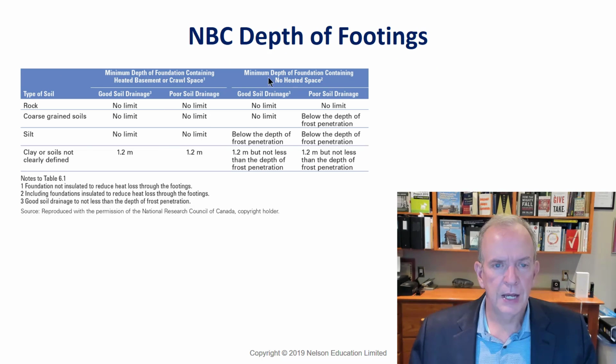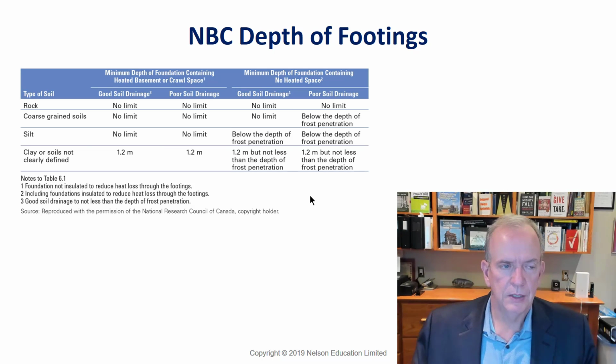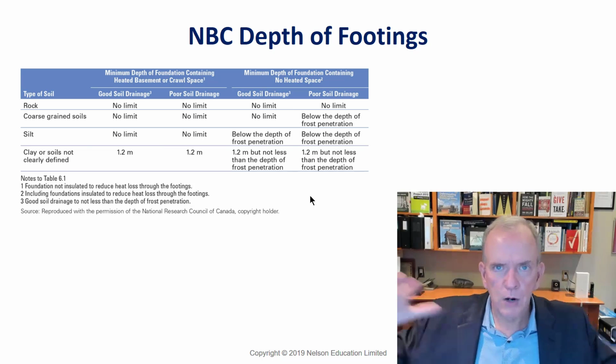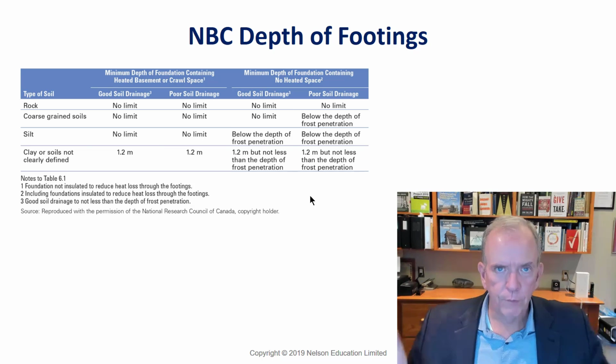This is straight from the National Building Code, pretty much the same thing in the Ontario Building Code. Minimum depth of foundation. So as we were saying, if you're on rock, you don't really have to worry about going down 4 feet, like the Canadian Shield. Everywhere is rock. Well, we don't have to blast out 4 feet of rock to put the foundation on more rock.